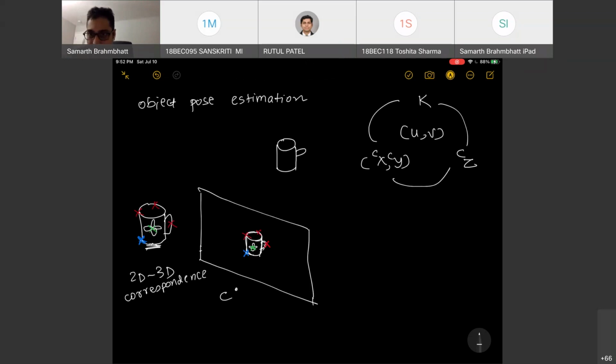Now let's say we have trained our machine learning and we know that. Can we use this information somehow to know the real position of the mug? So then the idea is we have calibrated the camera. So we know this calibration and we know these image observations. So then using that, we draw the rays. Right? So we draw a ray from here.